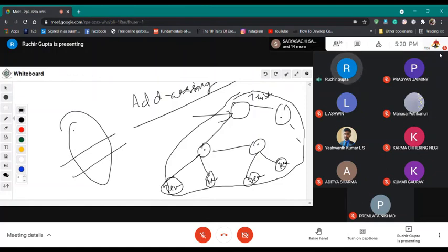And the whole root hub keeps on polling all the hubs and keeps on collecting information for new devices and for disconnected devices. When the host is informed that a new device has been connected, it sends a sequence of commands to the hub and then to the device, to understand its capabilities and send configuration information to the device.